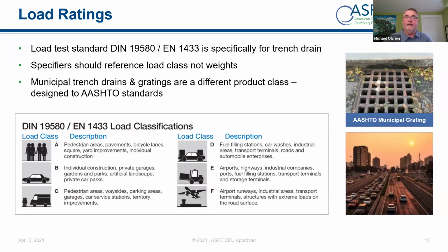So the load ratings, the test standard for trench drain is DIN 19580. It's a European standard, but it's the best choice for specification, and it's currently the only one specific to trench drain. I think there's an ASPE CSA one coming soon, but I don't have full details on that. And other load standards such as ANSI and H2O do not directly convert, but common sense conversions are usually sufficient.